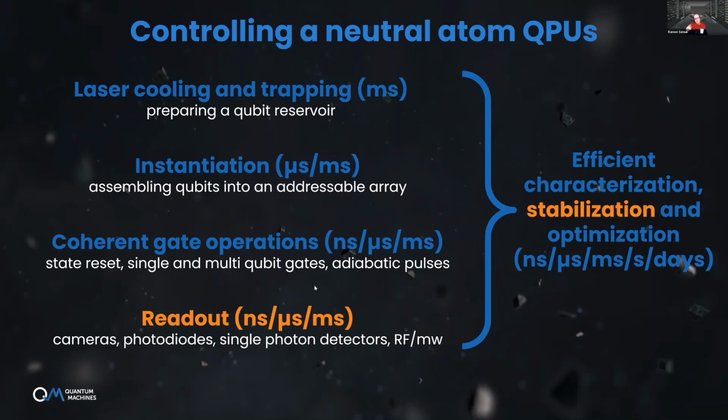If you change frequency and set a new phase at a different frequency, it will always come back to that phase when you come back to that frequency. So every frequency has its own phase, basically, and there is a perfect phase memory across all channels, even if you get more than one box, of course.